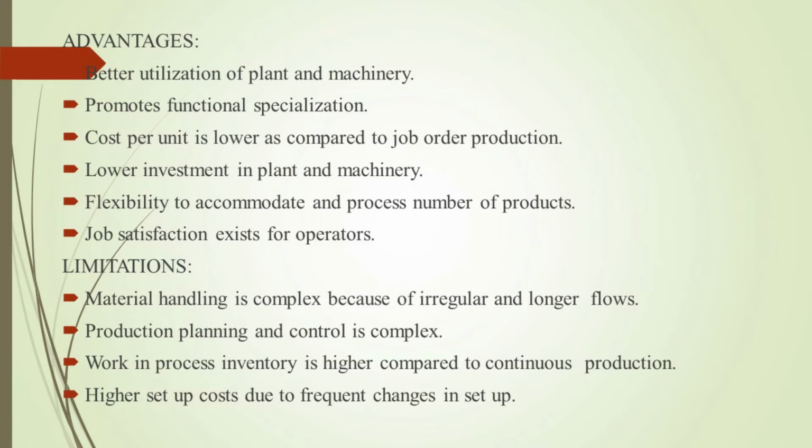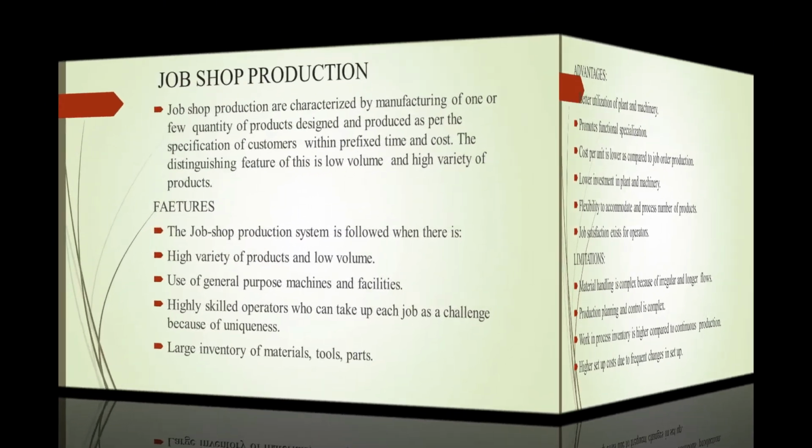The limitations are material handling is complex because of irregular and longer flows, production planning and control is complex, work in progress inventory is higher compared to continuous production, and higher setup cost due to frequent changes in setup.